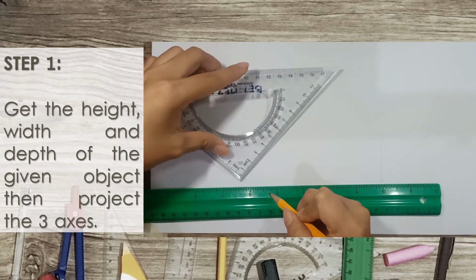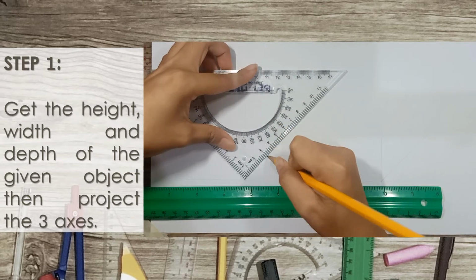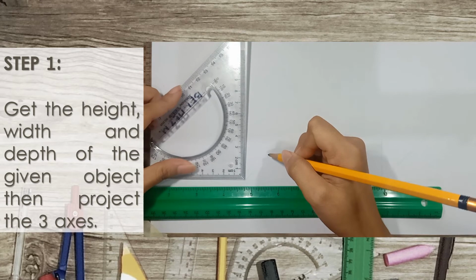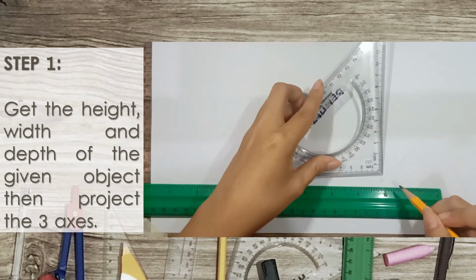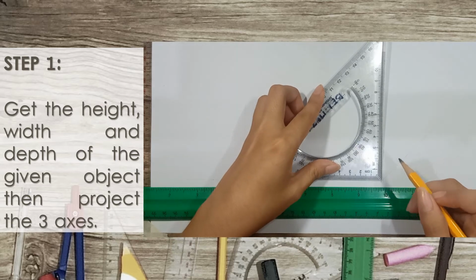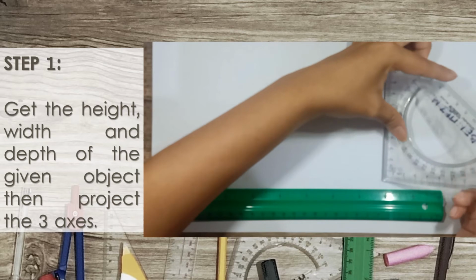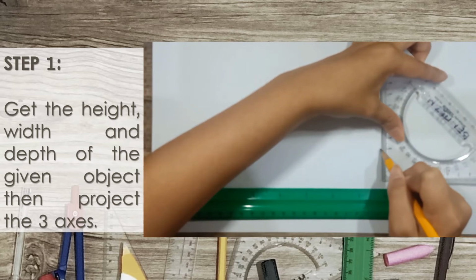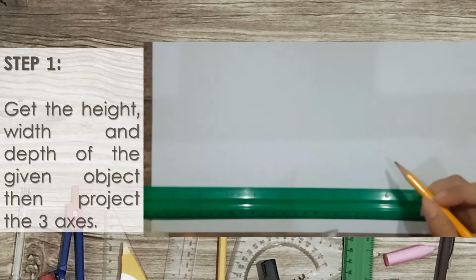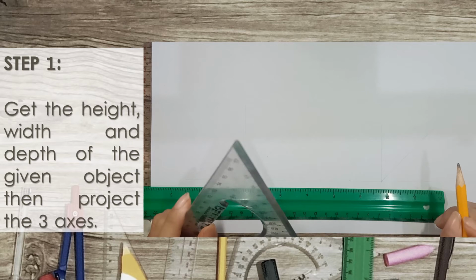So remember that in a cavalier oblique drawing, the depth will be drawn in full size. While in cabinet drawing, the depth will be half of its true dimension. So we have the true dimension of the width on the cabinet drawing, and then the true height, then the depth will be half of its true length.